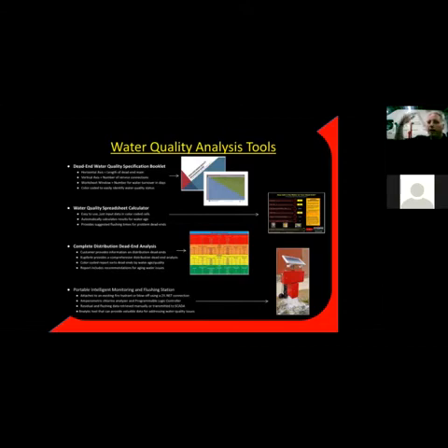So they sent me their data: pipe size, length of dead end, number of service connections, and I put it all into a spreadsheet. I sorted it by age, and the red section was the bad dead ends that they had. Out of 135 dead ends, they had about 21 really bad ones. And then the orange was kind of around 4 to 7 or 8 days, in the middle. And then the green ones were all the lines that were turning over every day, every other day, every third day, so they really didn't have any issues.